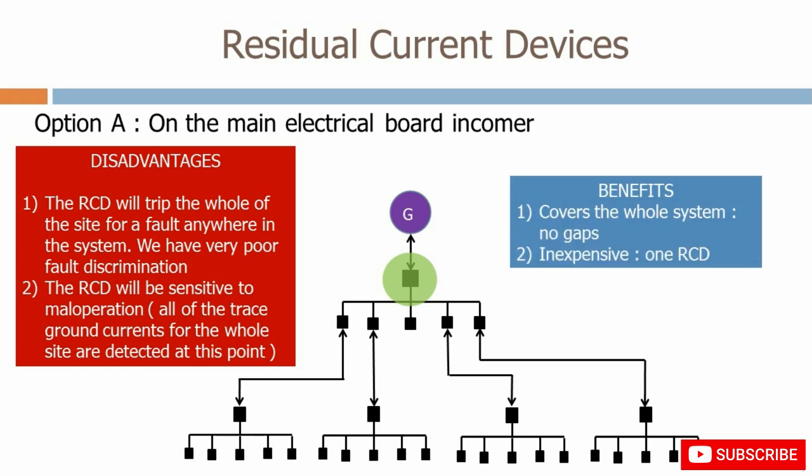The benefits are: the RCD covers the whole system. There's no gaps. This is an inexpensive option. We only need one RCD for the whole site.